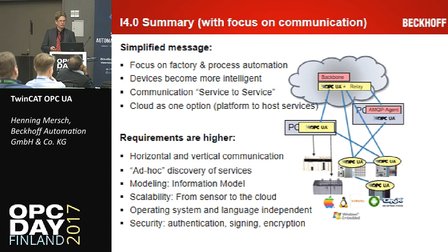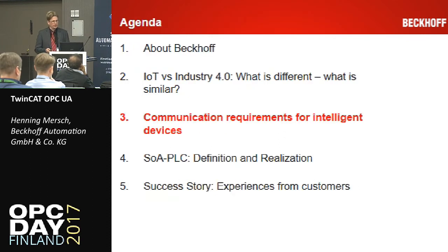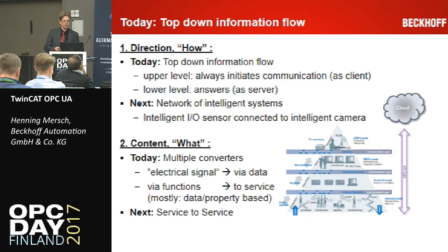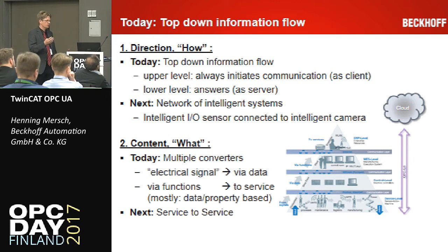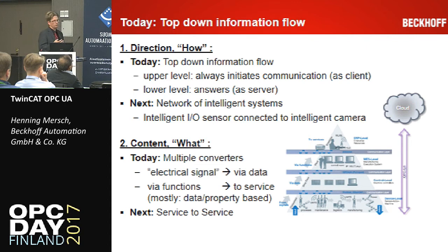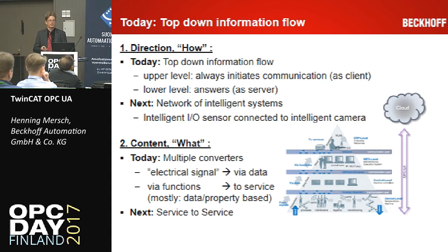So what are the communication requirements for these kind of intelligent devices? Today, we have more of this top-down approach. In established machines, we normally have the PLC, and the machine is acting as a server, so it sits there and is just providing access to its variables, or part of the variables of the program. But in the next generation, we think there's more bidirectional communication between different controllers.